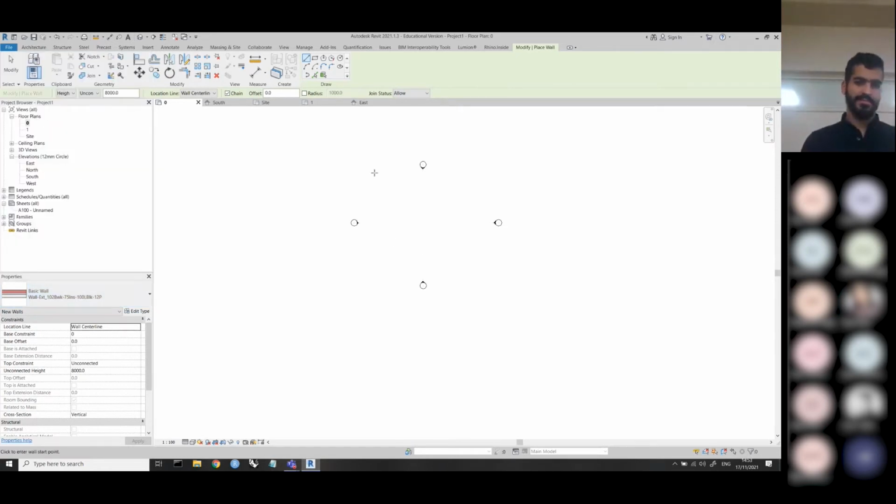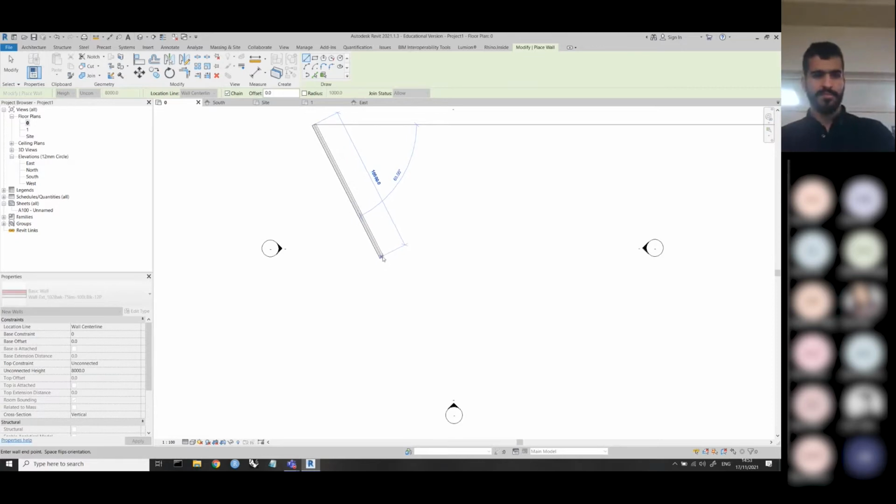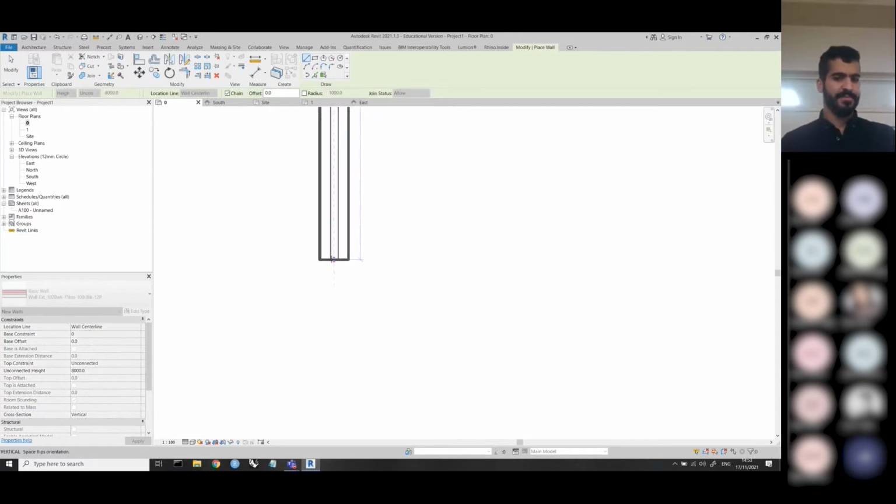So brick wall, and then you just draw it, right? So we'll go again. Just click on there, you have some options over here, right? Whenever you click on something or do something, always keep an eye on this area in Revit, because it'll either tell you something or give you other options. Location line, so I can draw a wall through the center here.